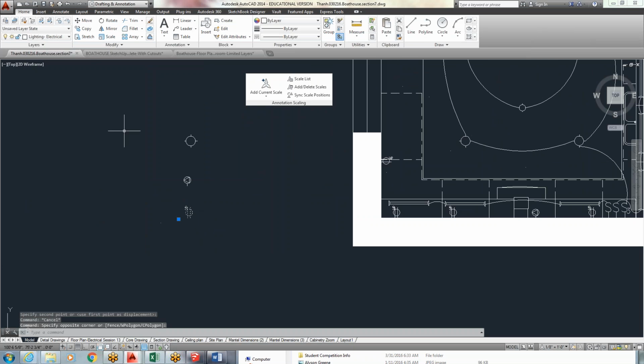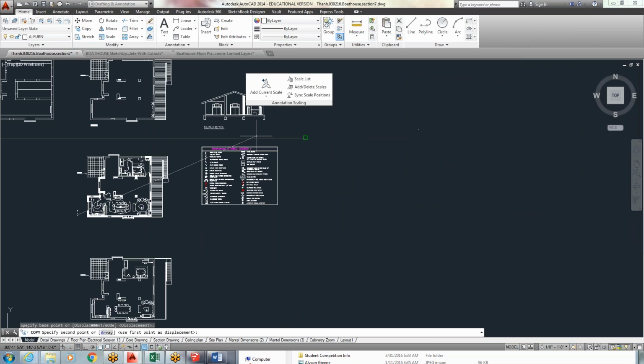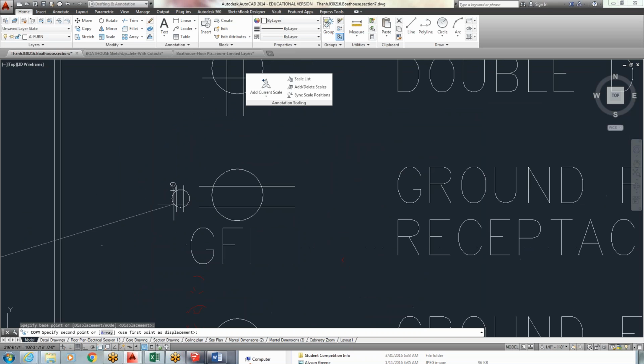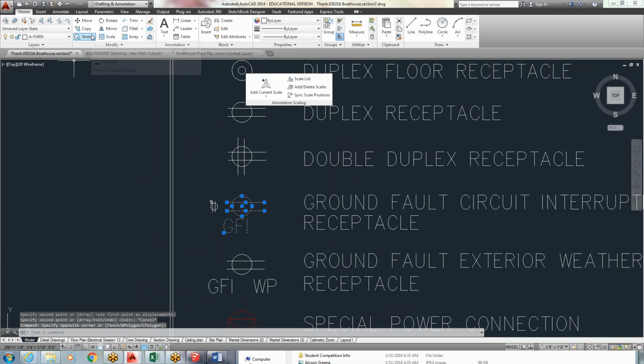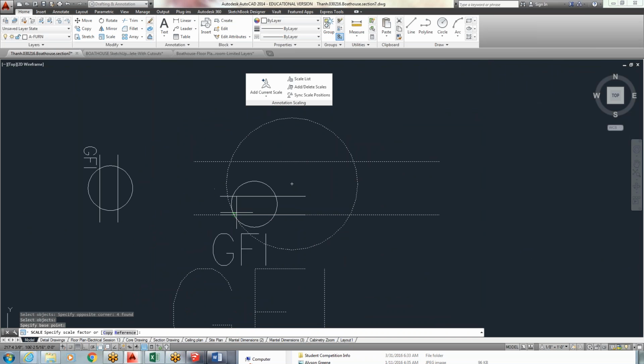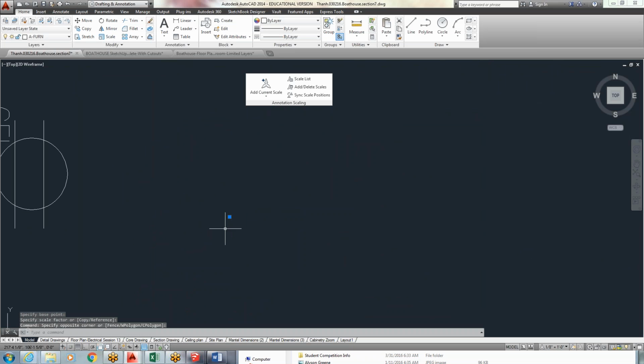So for instance, if I copy this object over to here, and when I say I gave you this, I gave it to you during the session for blocks, so it's saved hopefully somewhere to your computer because that was part of our session homework. But you can see these were a little bit overkill in the size, so I scaled them down. All I did to do that was select the object. It was already in pieces that were scalable, so I came through and grabbed the scale tool, hit enter after selecting it, picked a point to scale it, and I clicked it about that point.